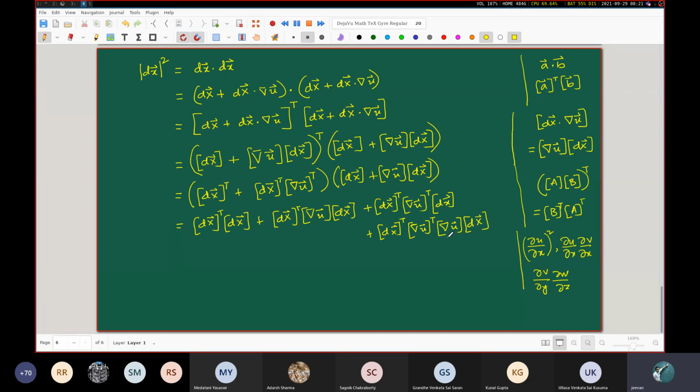Now, the entire thing that we are going to discuss will be associated with small deformations, small strains, and within that scope, these nonlinear terms are going to be extremely small. Individually, del u, del x, or del v, del x, or any of these terms will be of the order of, let's say, 0.01 or even smaller. Suppose a term is of order 10 to the power minus 2 or 10 to the power minus 3. You imagine the second degree version of that. What is it?